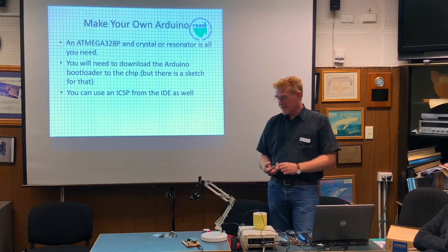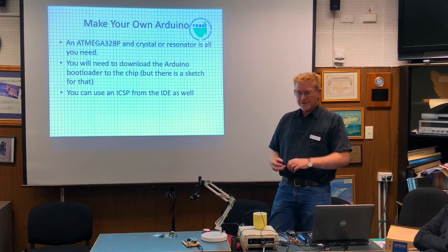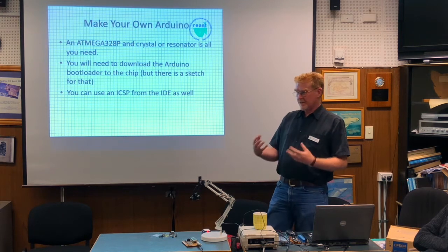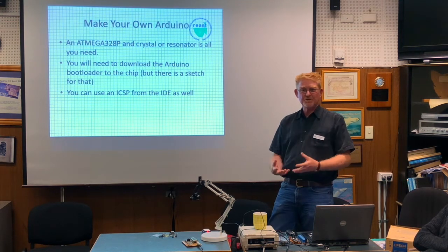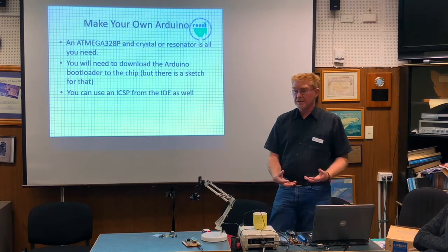Another way you can do that is, for instance, with the breadboard Arduino shield I showed you, you can actually plug your unprogrammed chip in there, wire up the programming pins, and download from the Arduino environment a sketch to program the thing for it. So you get Arduinos making Arduinos.